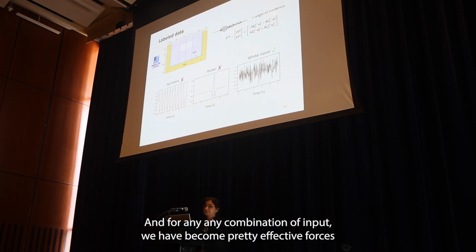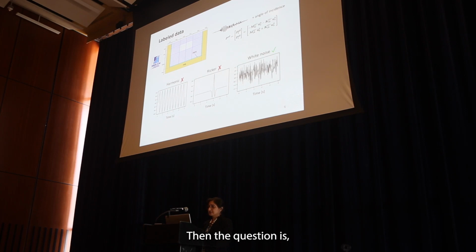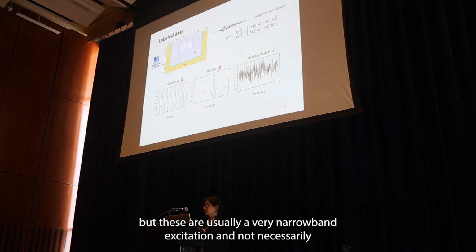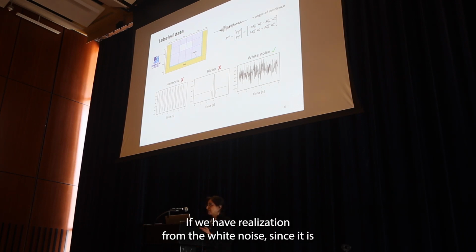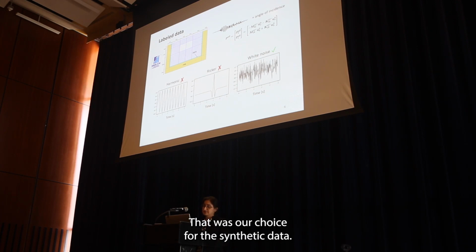And for any combination of input we have, we compute the effective forces, and then we can compute the response of that buried structure. Then the question is, we want to use synthetic data and short duration, but what type of synthetic data? So we tried harmonic and also Ricker wavelet, but these are usually a very narrow band excitation, and not necessarily can they reproduce the response to broadband excitation like the earthquake. And then we tried the white noise, and we noticed that if we have a realization from the white noise, since it is broadband enough, then we can successfully predict the earthquake response. So that was our choice for the synthetic data.